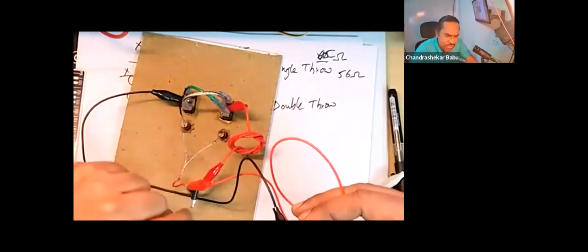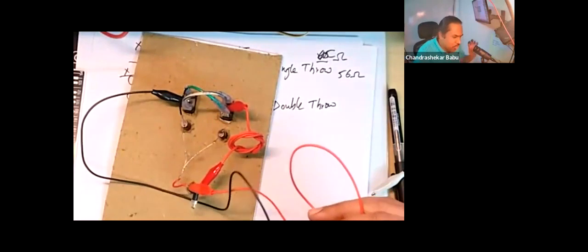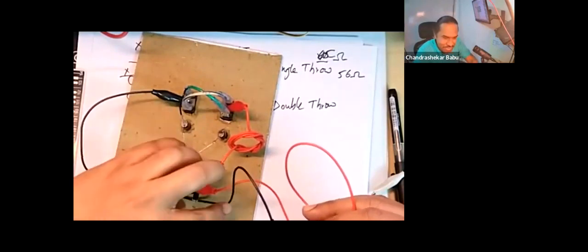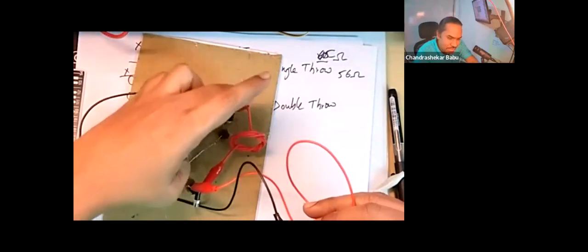There's no resistor for this because it's a green LED. A green LED will work without a problem on a 3-volt battery. Generally, the activation voltage will be around 2.8, 2.9 volts. You don't need a resistor. It just works. Of course, having a resistor is generally a good idea, but I just use it without a resistor for now. I'm not turning it on for a long duration, right? So it's connected to this side.